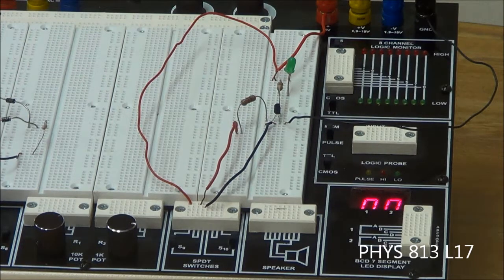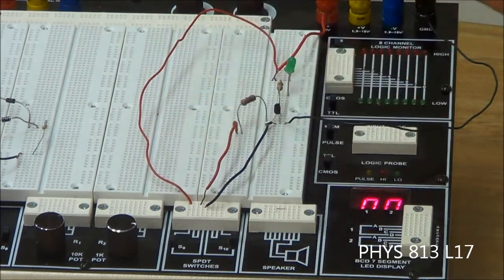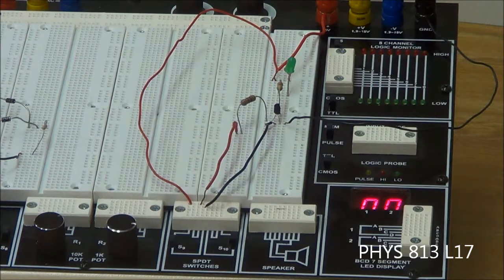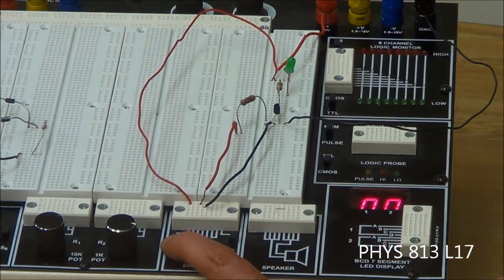Okay, so you can kind of put your hand over it, and if you feel a lot of heat, then that's not good. But I don't really feel anything, I don't see anything, and we don't smell anything. So everything should be fine. Okay, so that is step 7. Now, in step 8, it says if everything seems to be fine, then you want to move the switch. So I'm going to move the switch from the down position to the up position.